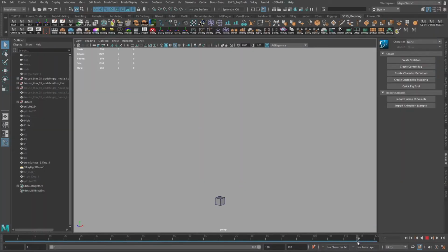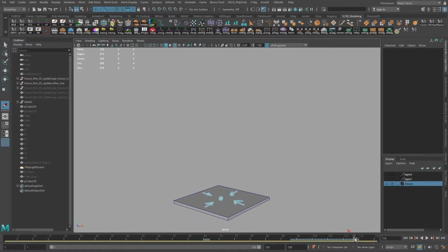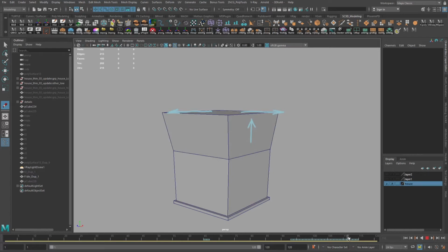Let's create a cube. Make a shape from the cube as the foundation for the house. Now extrude and tweak the offset. Extrude the top, extrude it again and scale a bit, and extrude it one more time. Select and merge the top vertices to the center in order to get a triangle shape. Select the top faces of the roof and extrude it.